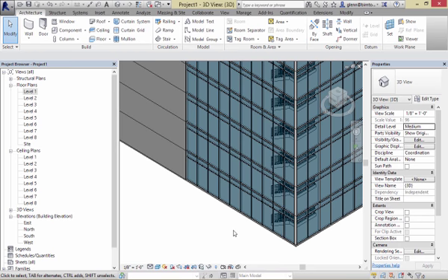Okay. If you have a break, maybe your building has a bigger floor-to-floor height on the lower floors because it's commercial space or industrial space, and then it changes, no worries. Do 1 through 5 as one stair, and then do 6 through 10 as another stair. As long as floor-to-floor height's the same, and in most of our commercial buildings anyway, it tends to be very, very similar. There may be small differences.